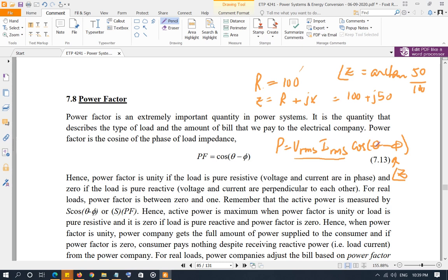So with the current that you're pulling, if you have inductance, let's say you have motors, you have a home industry and a bunch of motors, to establish the field in the motor through electromagnets, of course you have to pull a lot of current. But the watt-hour meter that you have at your home cannot measure that. It can only measure the active power. Any power that is going towards the inductor to establish the field is the reactive power.